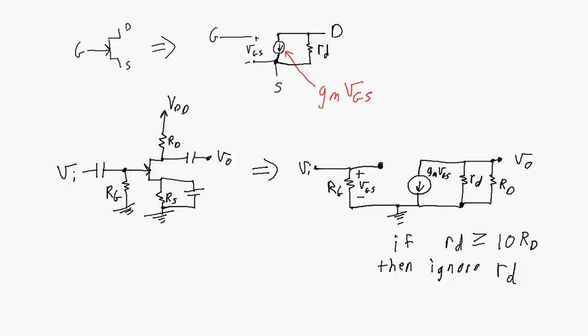Okay, the next videos are going to be showing how to convert this particular circuit into an amplifier model. So that small signal model, convert it into this model where I have my Z in, I've got my voltage gain, AV times V in, and I've got my Z out. So basically I'm just trying to figure out these three parameters. What's the input impedance of that amplifier? What's the output impedance of that amplifier? And then what's going to be the voltage gain of that amplifier.